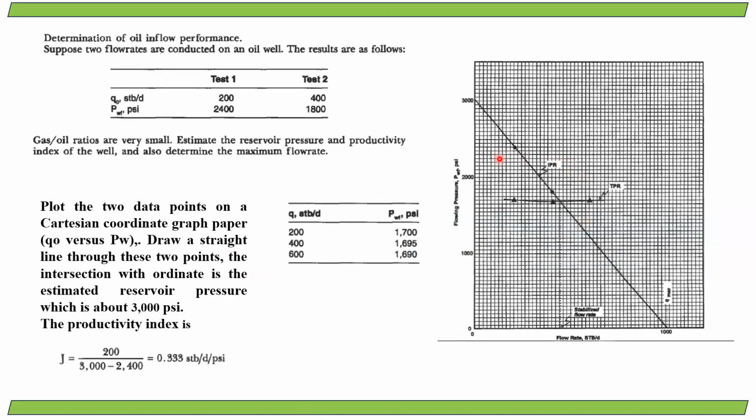So one is to find out reservoir pressure, and at the same time we have to get the value of maximum flow rate, that is AOFP. And if you want to do some adjustment, like changing the diameter of tubing, whether that is suitable to give best production, we have to estimate with this table. You can see another table is there, three different flow rates at three different pressure drops. So this is also IPR data when you change tubing diameter.